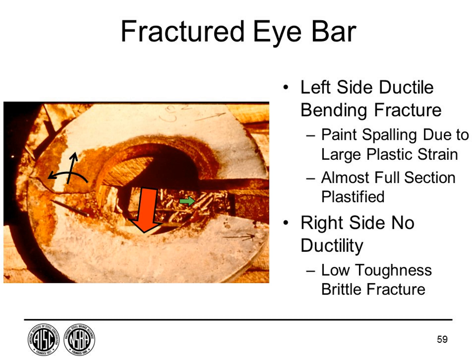What happened is this is the brittle fracture where it failed first, and you'll notice there's no evidence of any ductility or thickness reduction. But on the left-hand side, if you look, you'll see this pattern here. That's an indication we've had a lot of plastic deformation because the paint has fallen off. And so we had almost a plastic hinge form. This opened way up, a very ductile failure, and finally this failed, and that's when the bridge went.